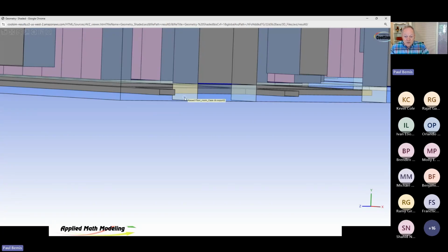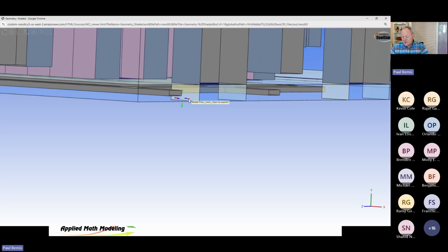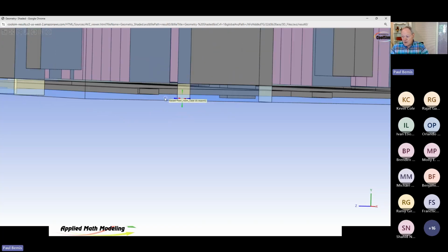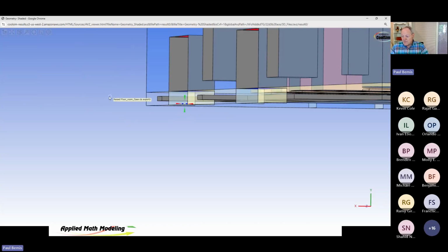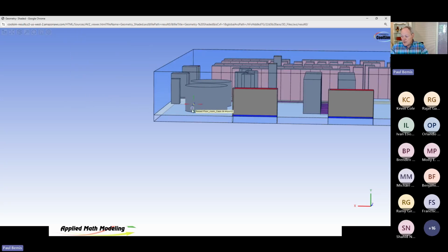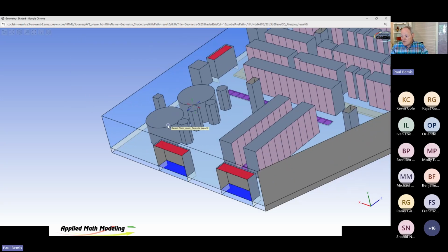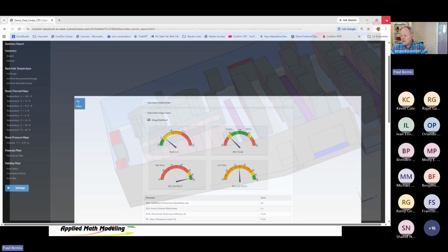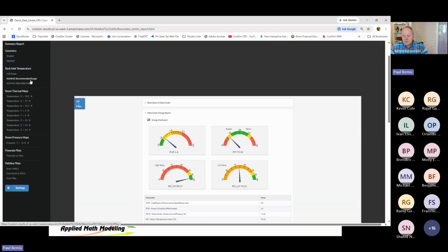Again, we go to Bernoulli, right? If the subfloor is not deep, you're going to have a high velocity, right? Because the cross-sectional area is narrow, and that means in order to get the mass flow through it, the velocity is going to go up. When the velocity goes up, the static pressure drops. Remember, they trade off with each other. Total pressure is static plus dynamic. So as this air comes rushing out, it's going to have high velocity. That's going to cause some issues. So there's my room itself.